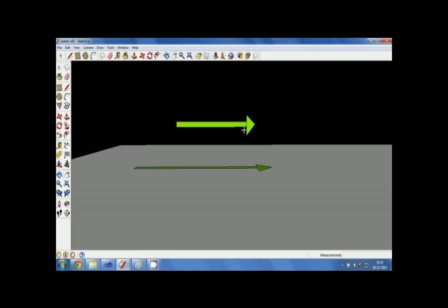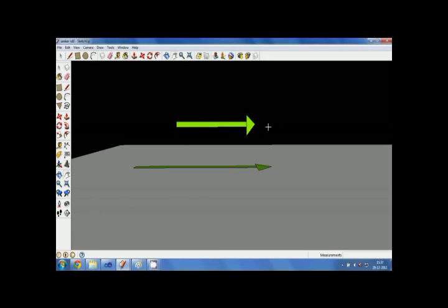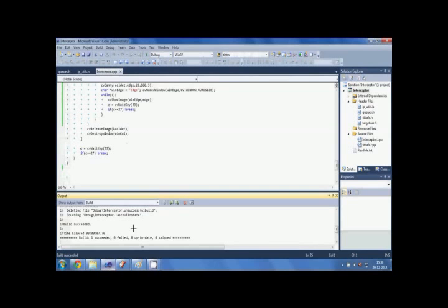So essentially while it builds, let's just have a look. We will want to detect this color, get an arrow with white suppose being the color of interest, the arrow will be white, and then we're going to analyze that blob, that arrow, and find out which direction it's pointed to or what it's telling us to do. Now bear in mind that you will know exactly whether this color is green or red or not, so you'll know exactly what category of sign it could be, so you can narrow down your choices there.